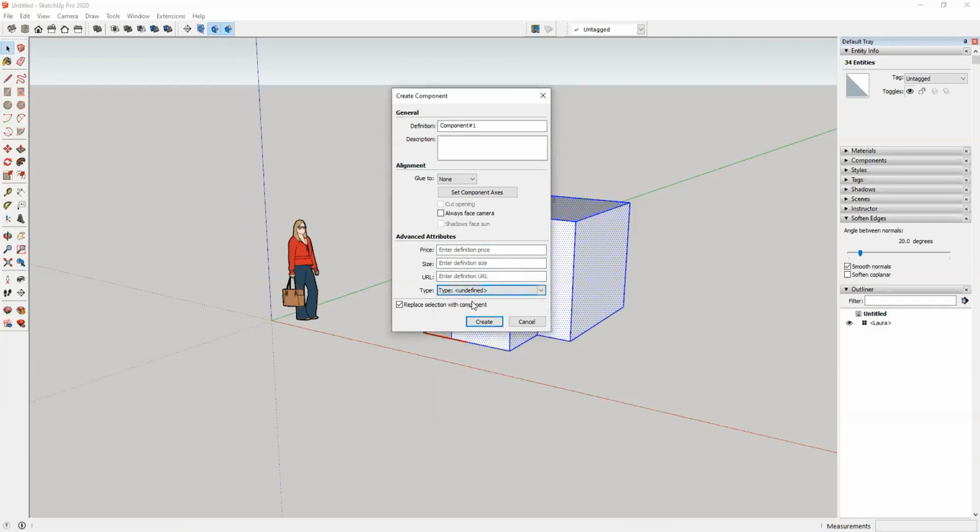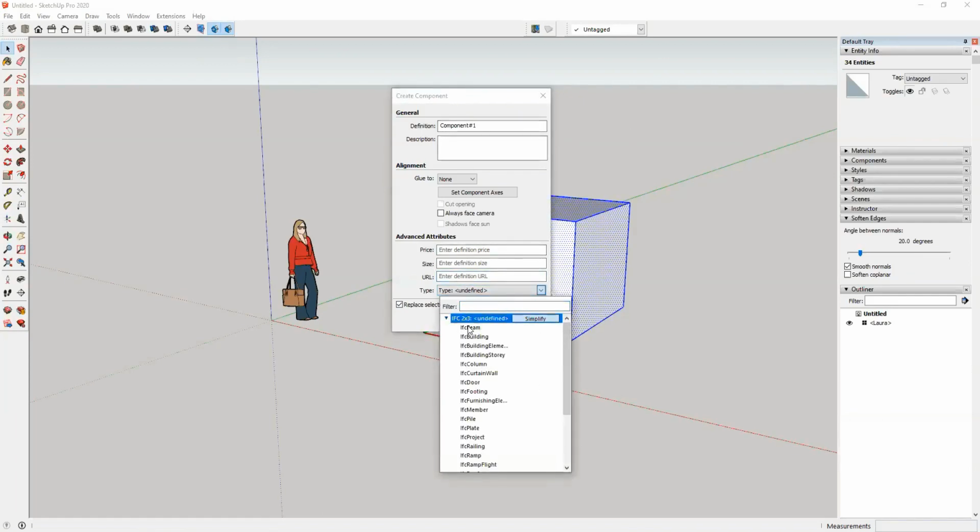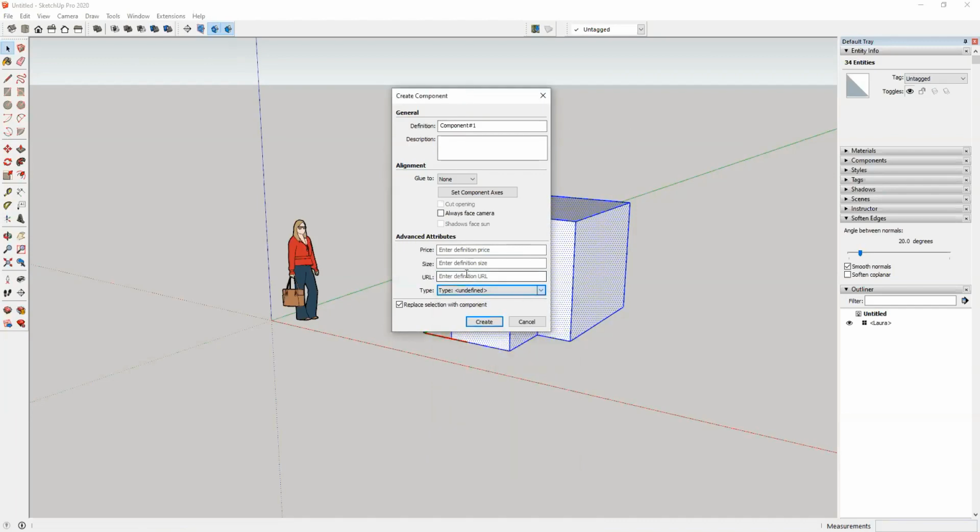Again, these are all features if we want to synchronize it with other BIM software. Then we need to define them. Like if we create a particular cuboid and define it as a wall, then other BIM software will be able to understand that it is defined as a wall. So if you are working with other BIM software, then you can use these particular parameters. Description is just the description of that particular component.